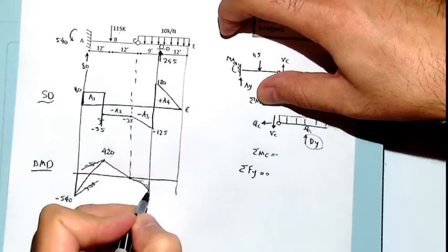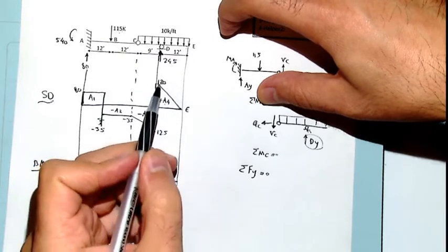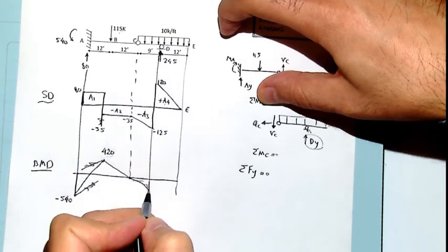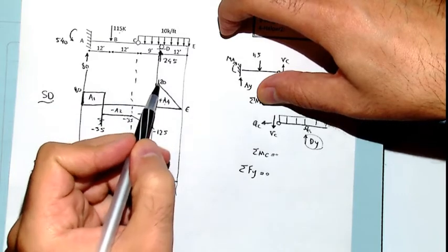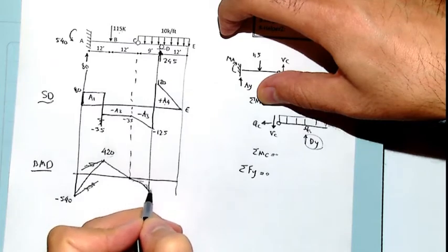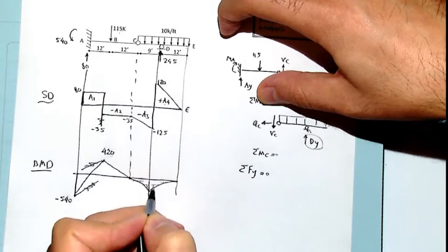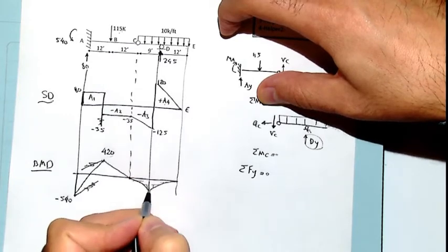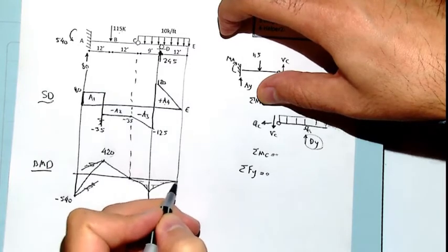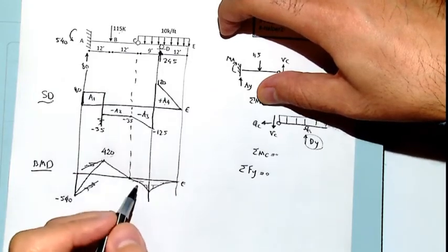After that, I have to add area number 4, which is 120 multiplied by this length divided by 2. Here it's from 120 to 0, it's decreasing, so the graph should be decreasing decrementally like this. And you see the difference. So the moment here is like this, and we have no moment here. It's true at point E. It proves that my calculation is correct.